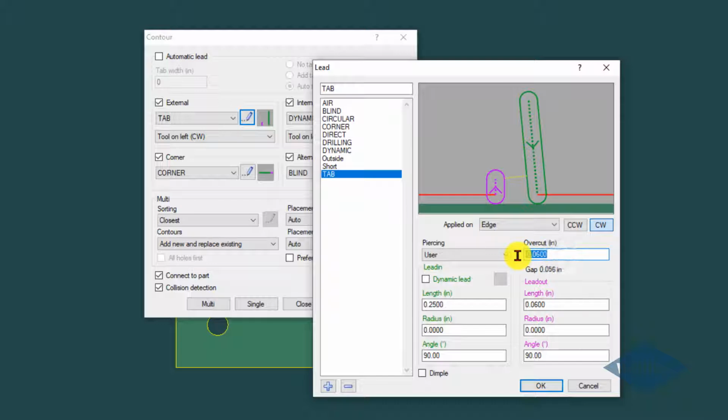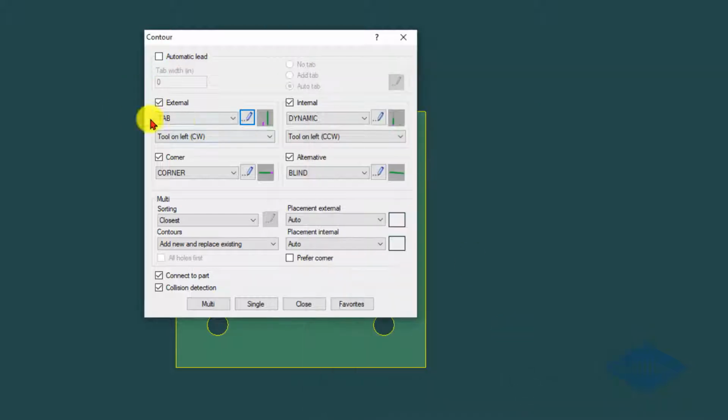And a negative number here means it's going to stop short, and it gives you an idea here how much of a tab you would be leaving based on the current nozzle orifice. So here we're showing about a 56 thou tab, which would be that yellow line there. So of course, if that's going to be too big, you can drop that down to 40 thou, whatever, as you change that, then that'll update accordingly. And then we've got that tab there.